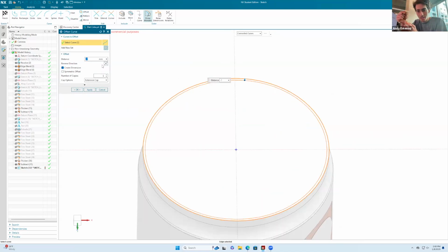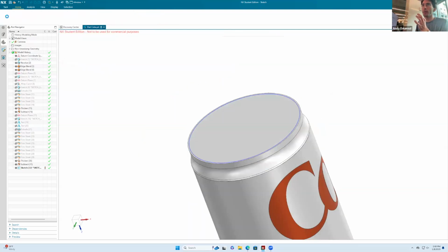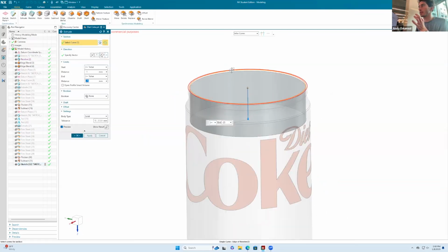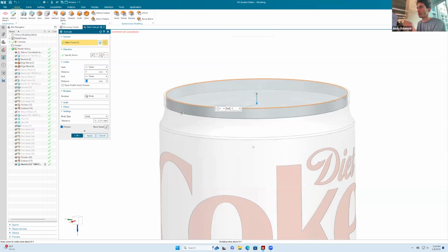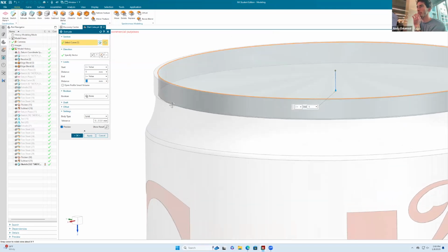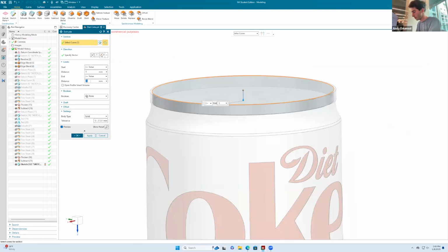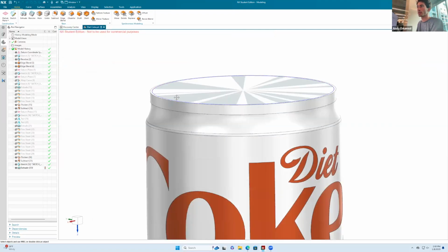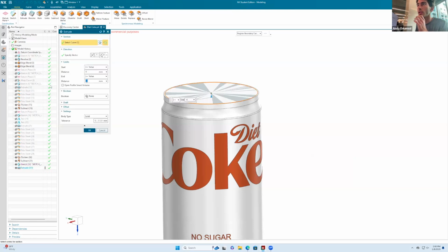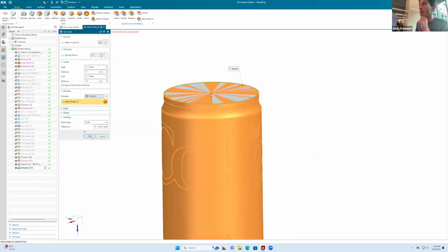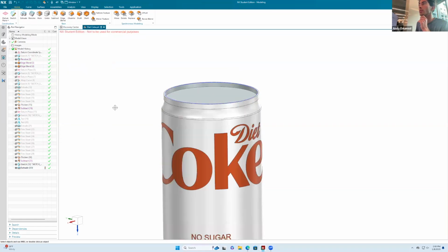Take that, the little aluminium part, the top, you can see it this way. I'm gonna extrude downwards by maybe -5 or so. Yeah, something along -4. And I should probably say here in edit parameters is that I want to subtract the body here. There we go.